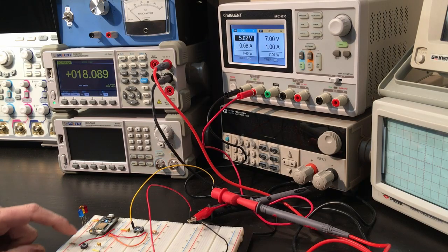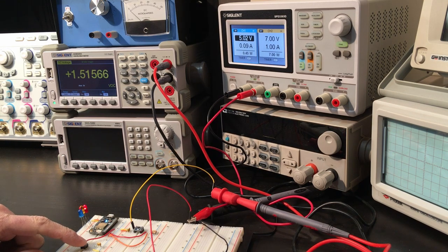To do the accuracy test, I set up a simple circuit with a push button, and every time I pressed the push button, I would increase the DAC value by 1/10 of its total resolution. Starting at 0, the first time I pushed it, the output value would be 1/10 of the total value of 4095, so 409. The second time I pushed it, it would output 819, or 2/10, and 3/10 and so on until I got through 10 pushes, in which case it would output the full value of 4095. Let's see what I found.